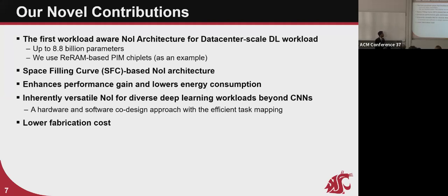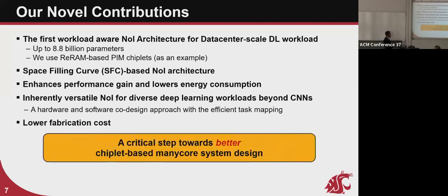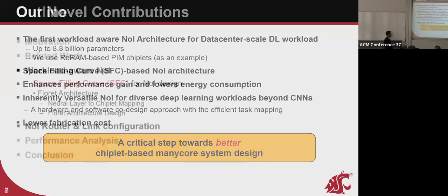We use a space filling curve-based NOI, and I'll talk about why space filling curve and what they are. We enhance performance and lower energy consumption, and we have this inherently versatile NOI for deep learning workloads which are beyond CNNs. We use hardware-software co-design, good for this track, and we also lower the fabrication cost, which we talk about later. So it's a critical step towards making chiplet-based ecosystem design more accessible.